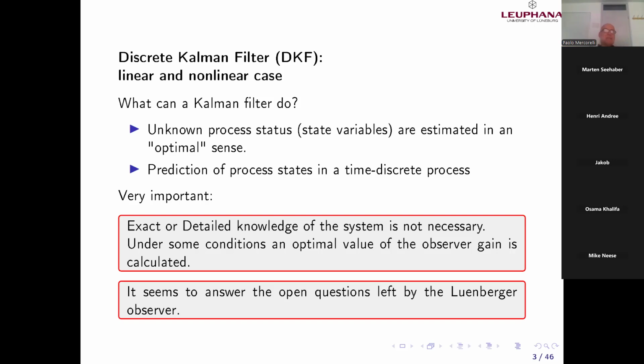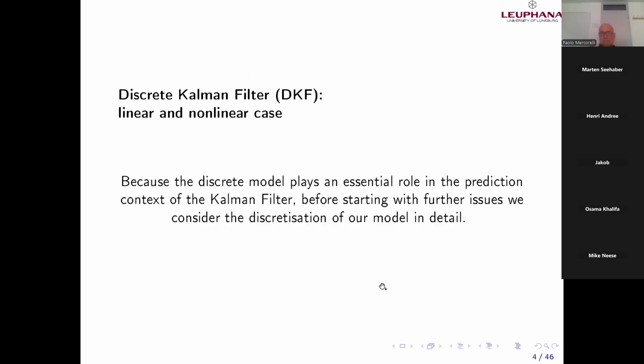We distinguish, we will see here in the Kalman filter, between measurement noise and model noise, no? System noise. In the sense that everything which we don't know, something which is uncertain, we represent as an uncertainty, can be classified as noise. Model noise, system noise, depends on the nomenclature, and measurement noise.